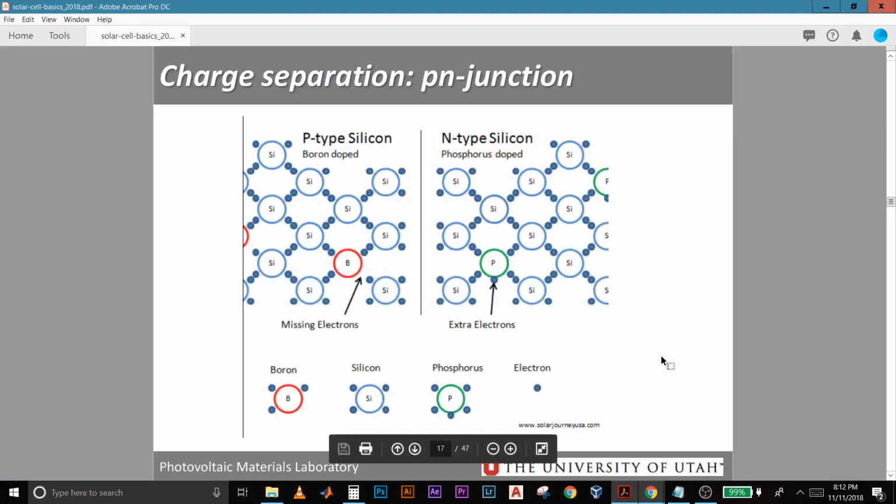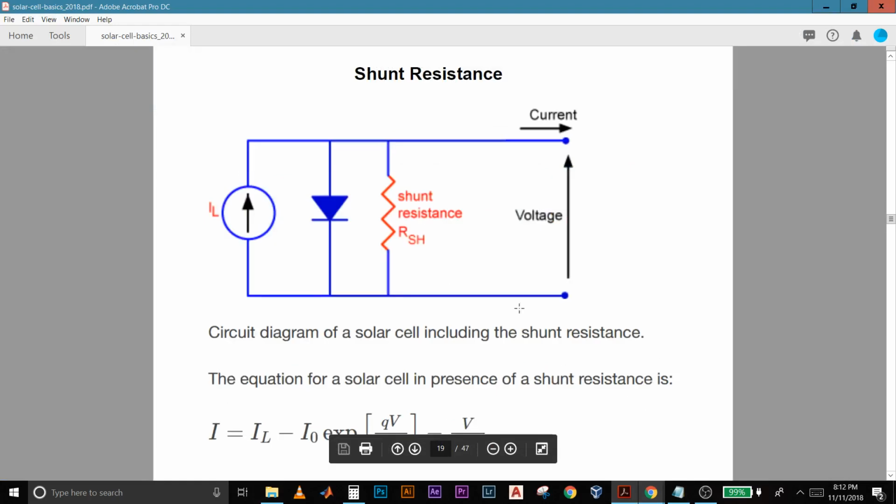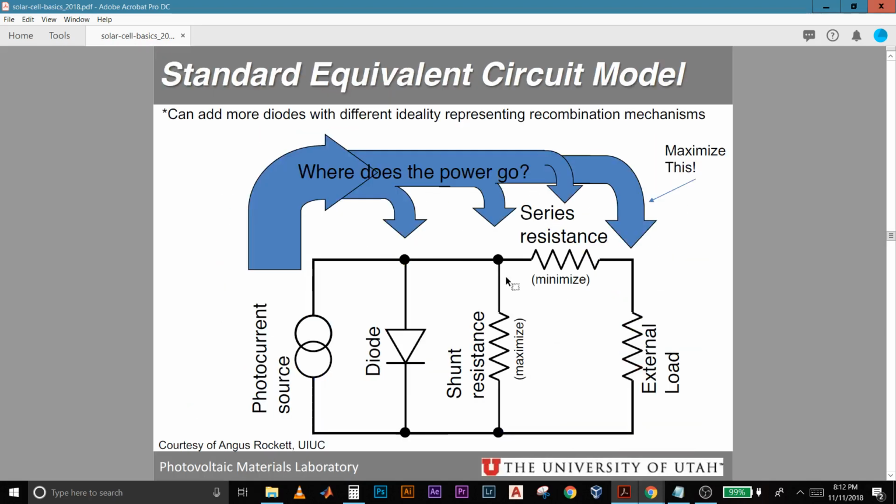So when we have to write the equivalent circuit of a solar cell, we write it like this. It's a combination of a photocurrent source. You see, this is a current source, IL, a photocurrent source, and a diode. These two we saw from the video, the diode type behavior, which is caused by the PN junction diode formation, and the generation of electric current from photons, basically a photocurrent source. I'll actually skip to this slide. It shows the photocurrent source and the diode.